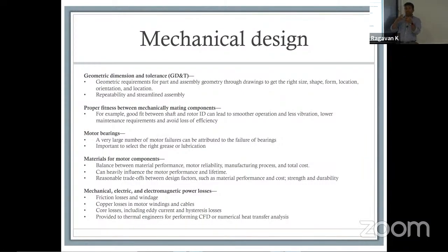If not, if you have a coupling that basically has a wiggle space, or give, as we call it, if you have a little bit of slack on it, you will end up creating a slapping action. Over time, it is just like what water does to rocks, right? Over time, it will erode, and that vibration will continuously keep getting worse.